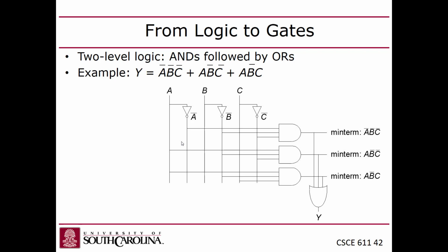So this is actually similar to the way real chips are laid out. If you look at an actual chip, there are these layers of what they call metal layers, which is the layers in which you can route wires. And they're layers because they're isolated with a layer of silicon dioxide in between them. And they give you the ability to connect together gates, essentially. But each layer alternates between vertical and horizontal wires. So this style of schematic sort of mirrors the actual layout of chips.